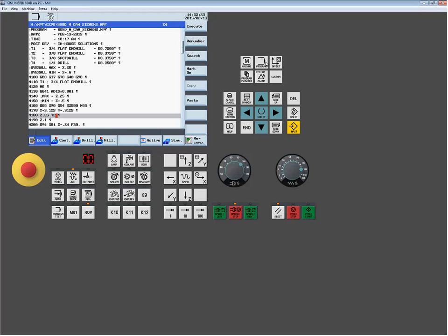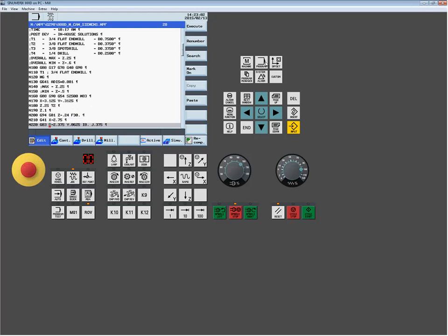But since the G41 is there, I either have to set up my tool with a 0 as my radius, and then as I adjust it, I can put maybe a small adjustment value here. And then as I simulate it, I'm going to get a new cutter path just off of that. So now, I'm going to zoom in for everybody so you can really start to see it. And let's move over a little bit. I want to get right in here. All right. So now I see, all I did was, in this case, I put 25 thou, a little larger than I would in real life, but I wanted you to get a chance to see the different cutter paths.